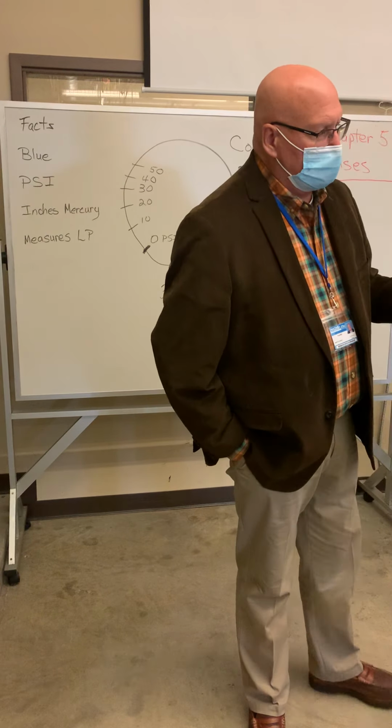So we have warm air that's being blown through an evaporator coil, which is much colder than the air in the room. The target temperature for the air in the room is 75 degrees Fahrenheit, so that return air is usually going to be slightly warmer. As we blow through a coil, the coil is actually 40 degrees Fahrenheit.